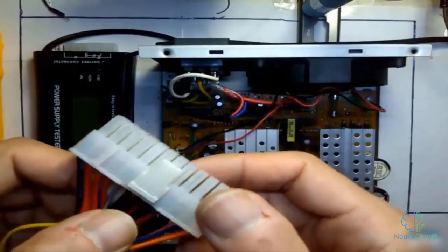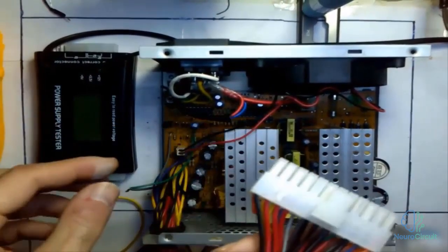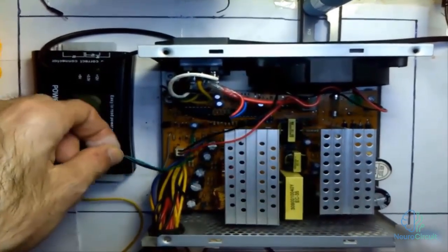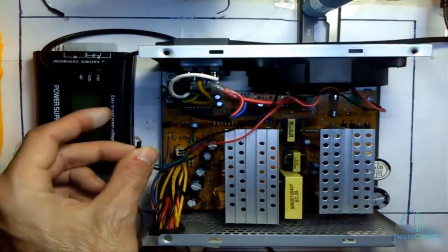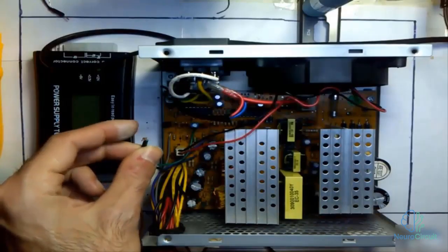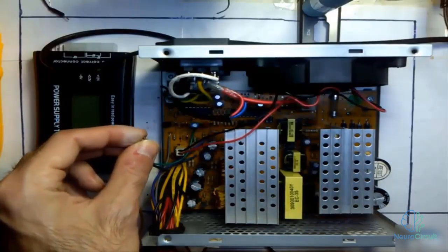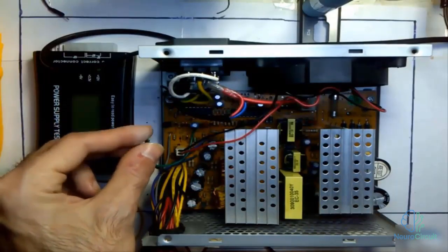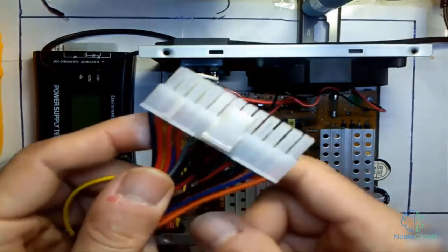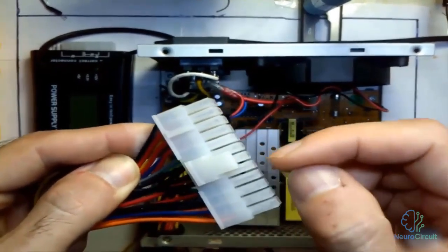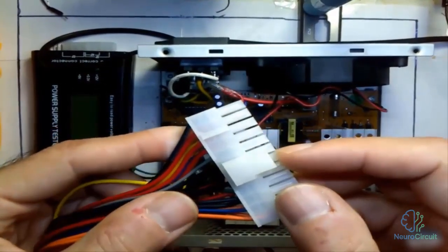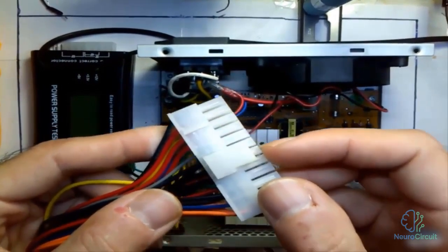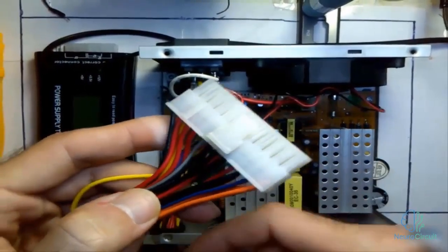If you want to test a power supply more thoroughly, you can completely separate the green and black wires like this, cut them, and then connect them together here. Which is what I did here, and I usually do this for test power supplies. But for power supplies that you want to repair and give back to a customer, you should never do this under any circumstances, and only connect the wires together at the connector here. The green wire is for turning on the power supply and carries plus 5 volts, while the black wire is 0 volts.